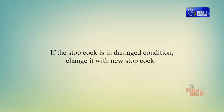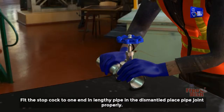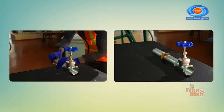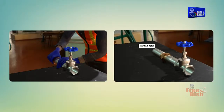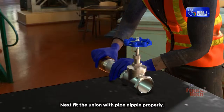If the stopcock is in damaged condition, change it with new stopcock. Fit the stopcock to one end in lengthy pipe in the dismantled place pipe joint properly. Fix the pipe nipple to other end of stopcock properly. Next, fit the union with pipe nipple properly.